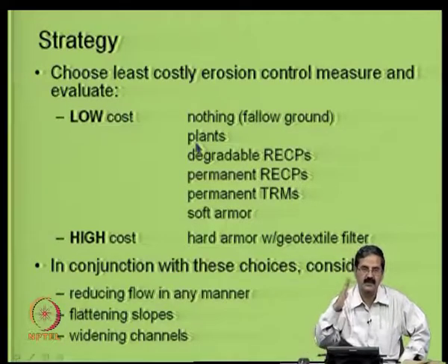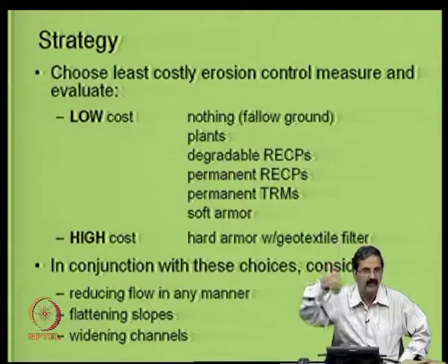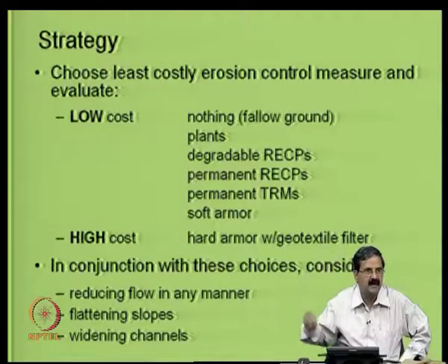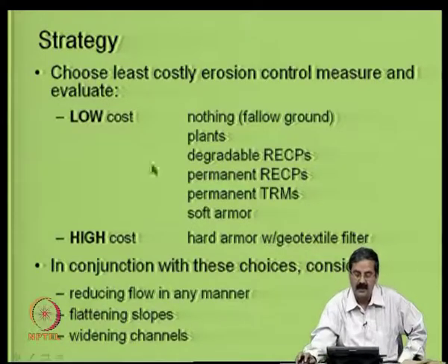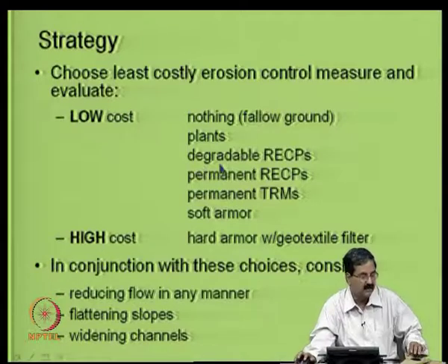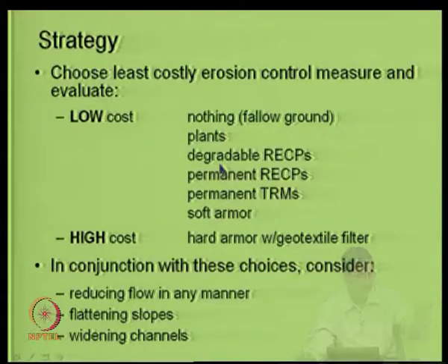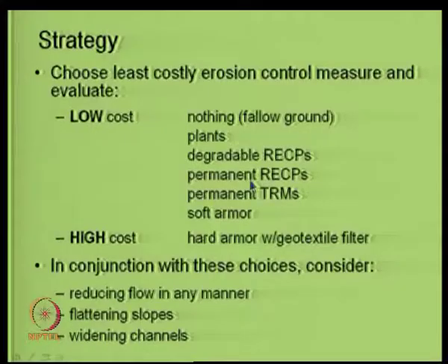Actually, if it is a very steep slope, the runoff will be high and the forces will be high, so you need to provide proper protection. So plants are one alternative. Then degradable materials like jute or coir one can use, and this coir and jute can be used to provide a sort of cover for this.